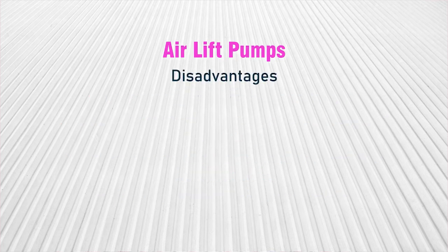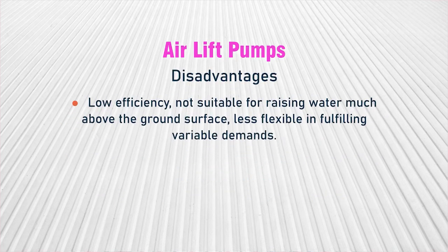When looking at the disadvantages of airlift pumps, one of the biggest disadvantages is that it offers very low efficiency of operation. These are not suitable for raising water much above the ground surface, and they are less flexible in fulfilling the variable demands of water. So keeping in mind the various advantages and disadvantages of airlift pumps, we can determine in which situations such pumps can be utilized.